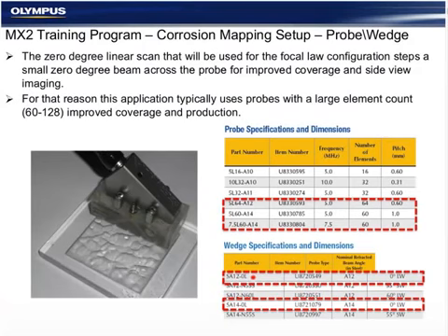These differ in frequency and pitch, so coverage and accessibility is our primary concern. We want the individual beam quality of a small UT probe multiplexed across a wide array for coverage and better imaging.